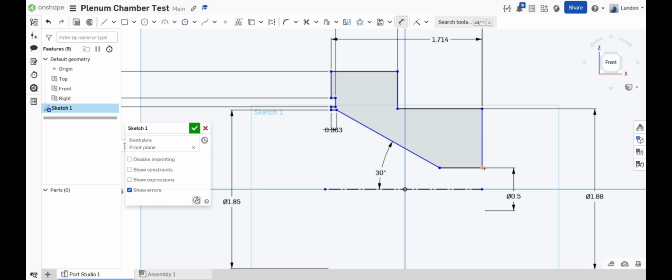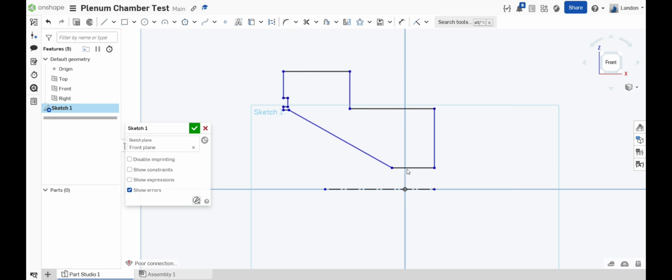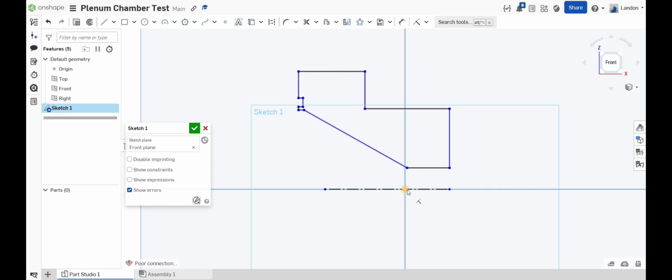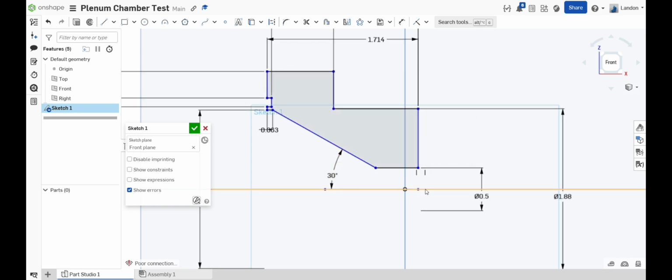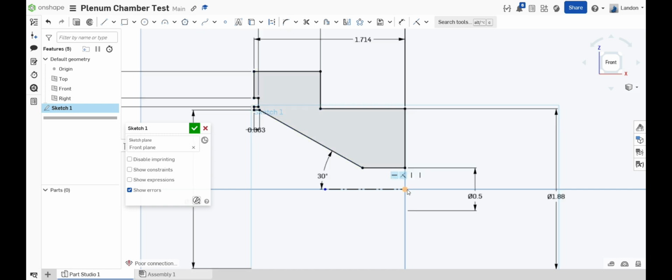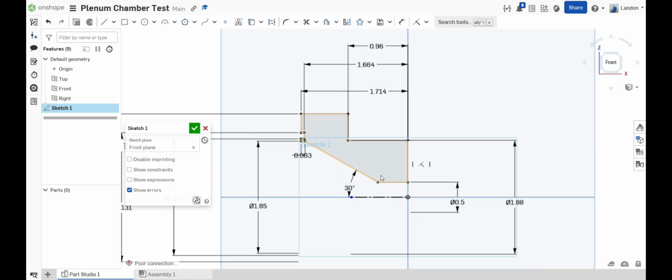Notice that even if we make this bigger, it won't change any other variable. Therefore, this diameter is pretty arbitrary as long as it's less than 45/64. What else here is undefined? Well, notice how we can move the entire thing? Let's just make one of the points aligned with the origin. Wonderful. Now everything is solid and the lines are black, which means everything is defined.